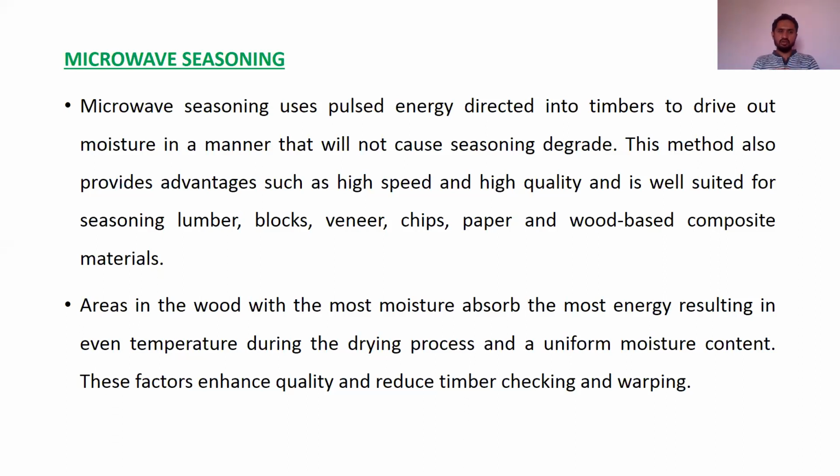Areas in the wood with the most moisture absorb the most energy, resulting in even temperature drying and a uniform moisture content. These factors enhance the quality and reduce timber checking and warping. So here what happens, as you are putting the timber into the microwave, there is a uniform heat production in the whole body of the microwave.